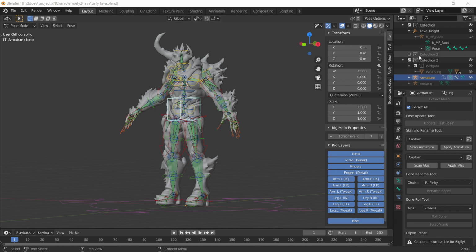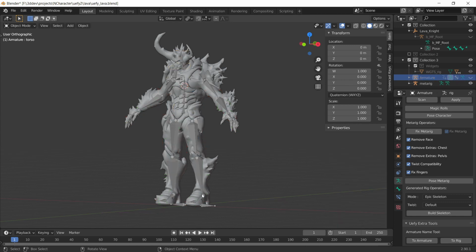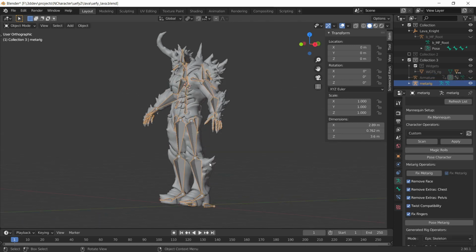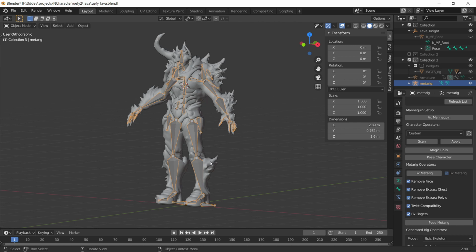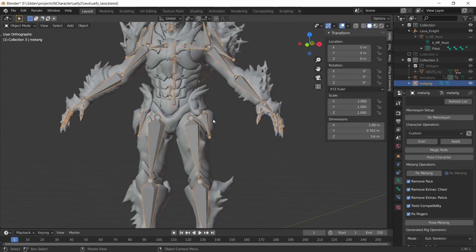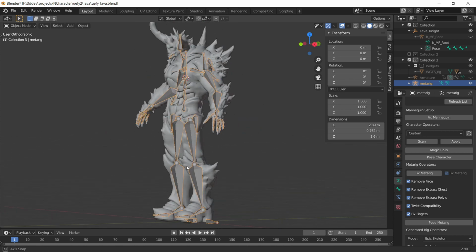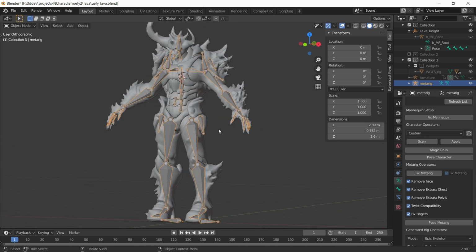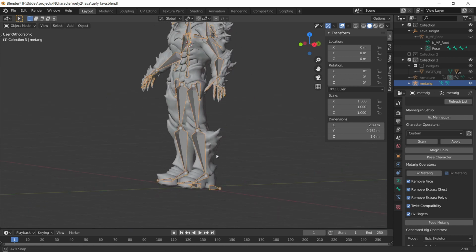Now, the preferred way to deal with this would just be to open up the Metarig again, like that, and simply add 2 additional bones for the boots, and that is perfectly fine. We could have built this entire character incrementally. We could have added the flaps and then did the whole generate rig and build skeleton, and then added the shoulder pads and then rebuilt it, and then again and again. So you could build this incrementally. We just did it in one single pass.